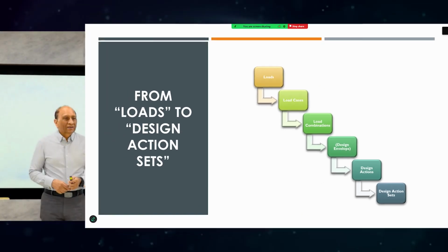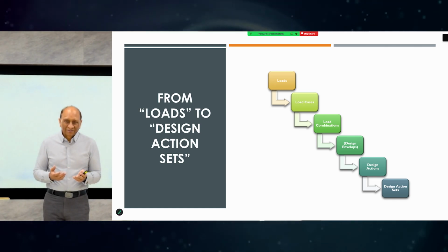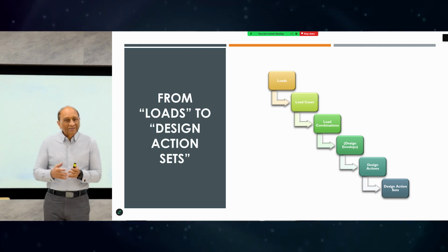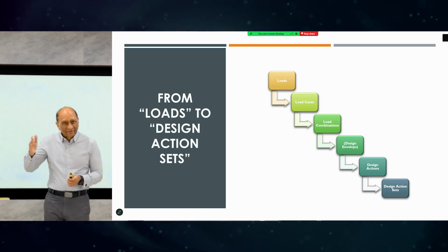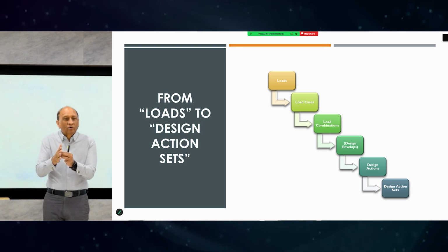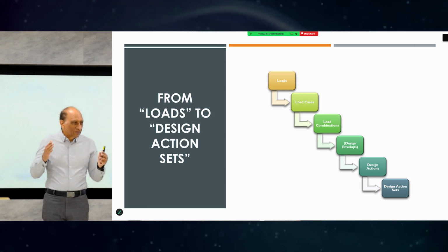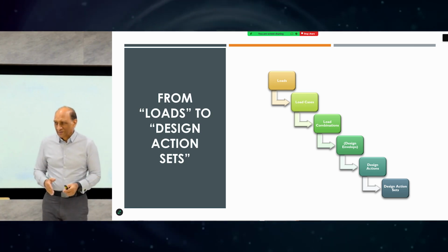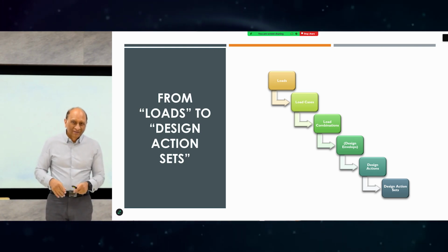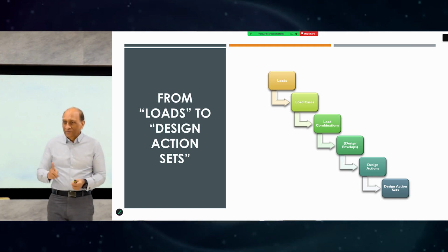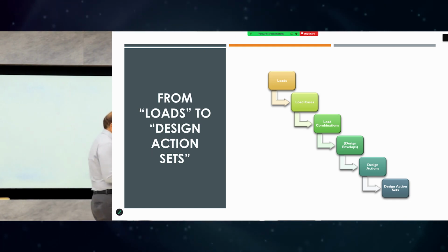Now imagine you're running non-linear time history analysis, which we will talk about later. You will get thousands of actions because at each stage of the ground motion, we are calculating each acceleration step, we are calculating all the forces. And one earthquake has 4,000 steps, let's say, or 2,000 steps. So the structure is being analyzed 2,000 times for every acceleration step. Every time all the interaction, all the combinations are being considered, you're getting hundreds of thousands of load combinations for each column and then getting reinforcement out of that. So it becomes a huge task in the end.